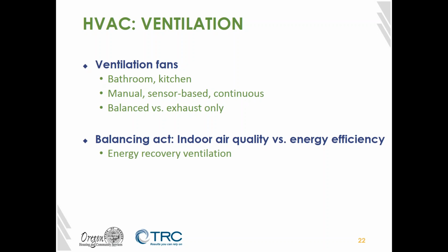Another thing for ventilation is when you turn on ventilation fans pushing air out of the building, it depressurizes the building and pulls air in. So if you want a more healthy building, you can control the air that's coming in by having a supply fan. But that is balanced on an energy aspect by the fact that you are pulling in unconditioned air and adding an extra fan. So it's a bit of an energy penalty there, but you do get a healthier building.